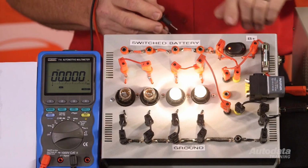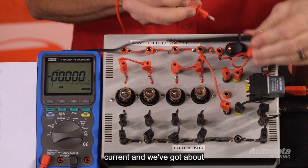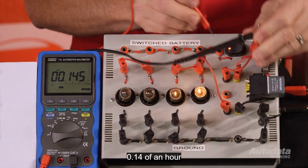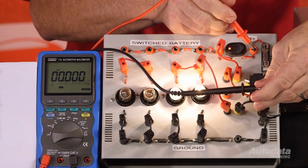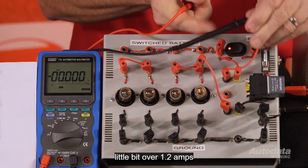Here I've got a relay circuit with 2 globes. I'm going to measure the coil current. And we've got about 0.14 of an amp. I'll measure the load current. And there we have a little bit over 1.2 amps.